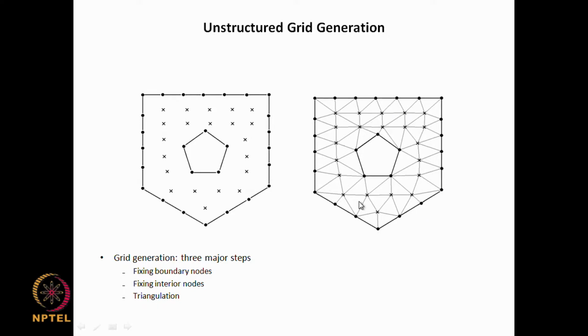Now, this is a very coarse grid, and we really cannot use it for CFD solutions with any kind of accuracy, but the idea is to go from there to here, and here we have a grid which meets those considerations: all the boundaries are part of this grid, the whole boundary is there, and all the computational domain is included as the area of the individual cells, and the sum of the areas of all the triangular cells is equal to the area of the computational domain.